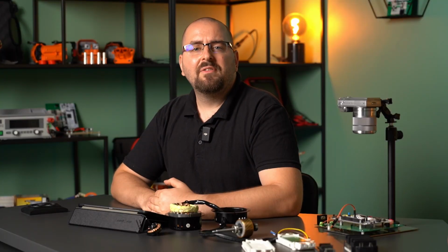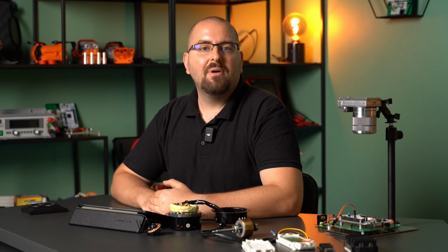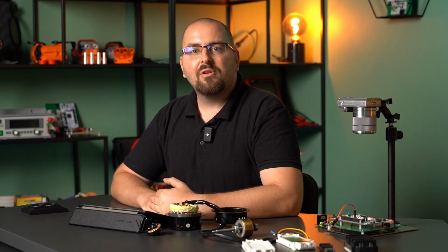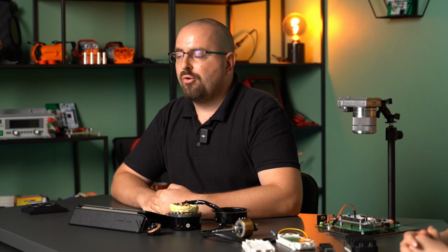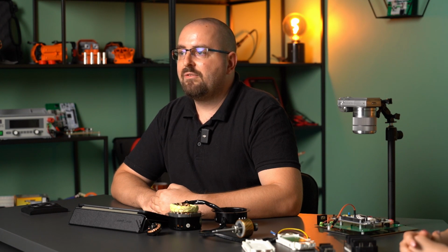As I've already mentioned, the motor I have in front of me here, called BLDC, is itself a three-phase synchronous motor. However, there is a subtle difference in the design of BLDC motors and normal synchronous motors. BLDC motors are usually square field, while synchronous motors are sine field. This means that if you rotate the rotor of a sine field synchronous motor at a constant speed, the magnetic field at a given point on the stator will change sinusoidally. Similarly, the waveform will resemble a trapezoidal square waveform for a square field motor. You can easily find this out about a motor by looking at the induced voltage waveform between its two outputs as you rotate its rotor, since the induced voltage will be proportional to the change in the magnetic field.